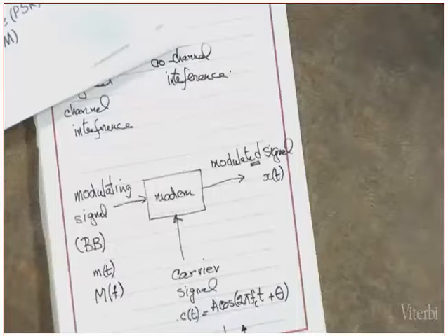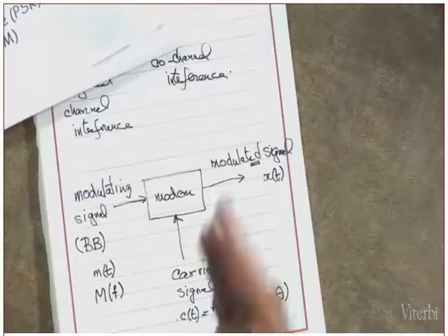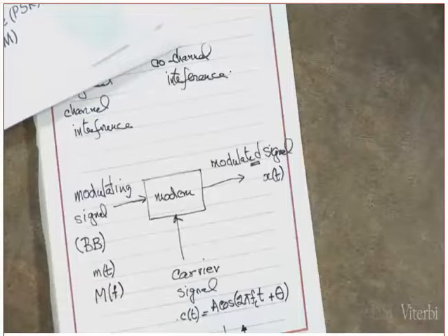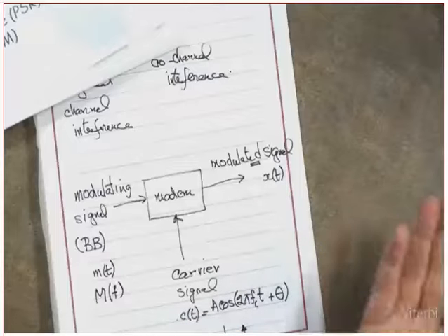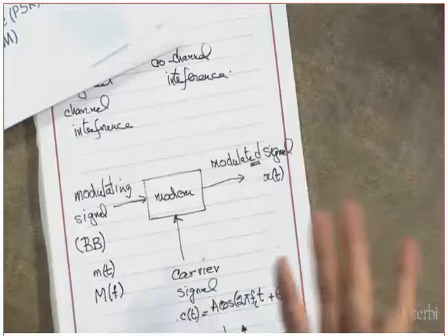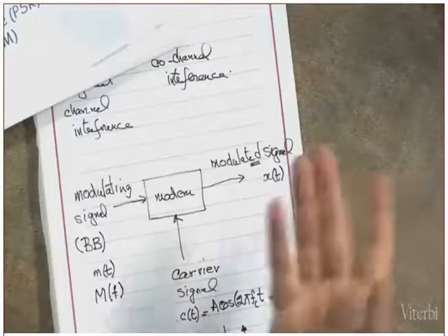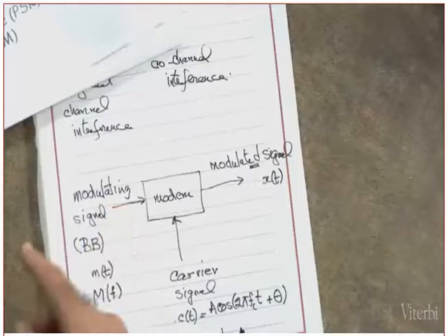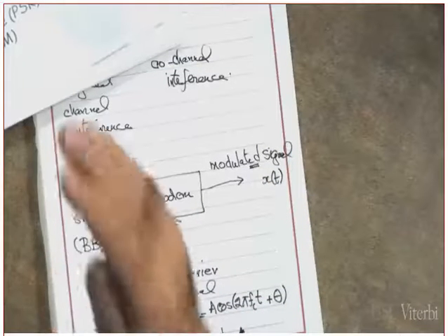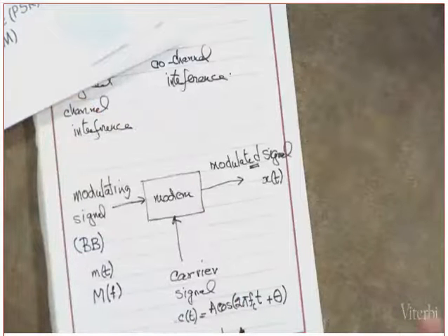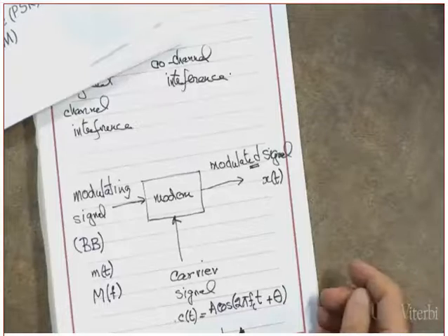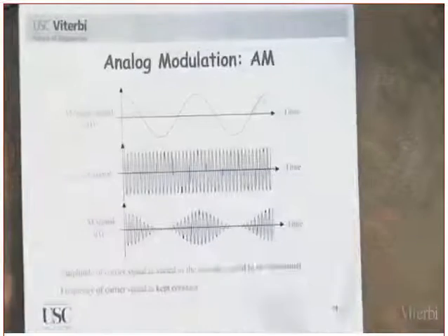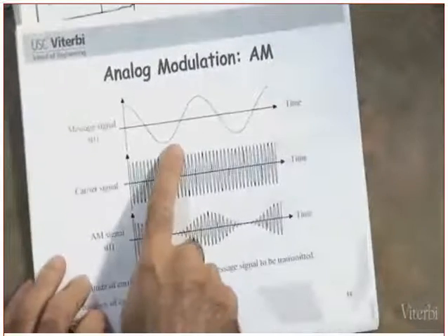So when you hear people talking about digital modulation, I don't want you to say the carrier is digital. The carrier is always an analog signal, but the information that it's carrying is digital information. Now, most of the time in this course, we are going to assume that the signal is digital. If the source happens to be analog, then I'm going to apply it to an ADC, analog to digital conversion, before I modulate. Clear? Okay, good.